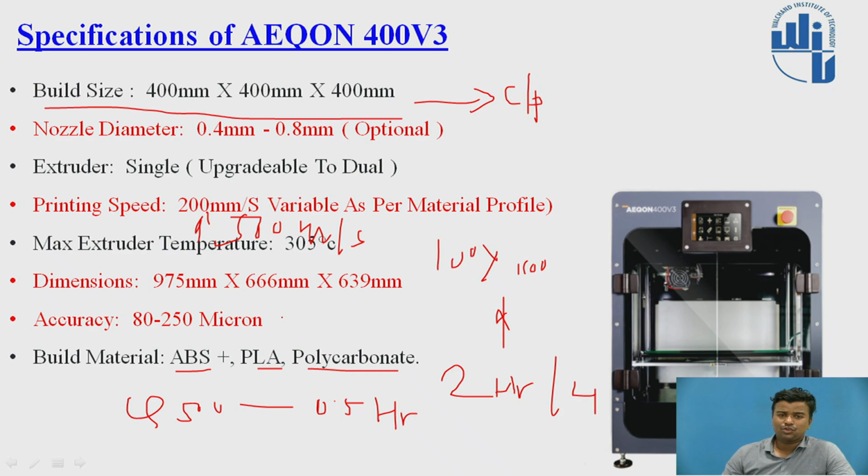Now there may be the question: do we have to change the extruder whenever we change the material? The answer is yes. We have to change the extruder whenever you change the spool, because the preheating temperatures for those materials are different. For example, thermoplastic urethane, TPU, is a very flexible material. If you want to develop a spring, which requires flexibility, you can't develop this application with ABS or PLA.